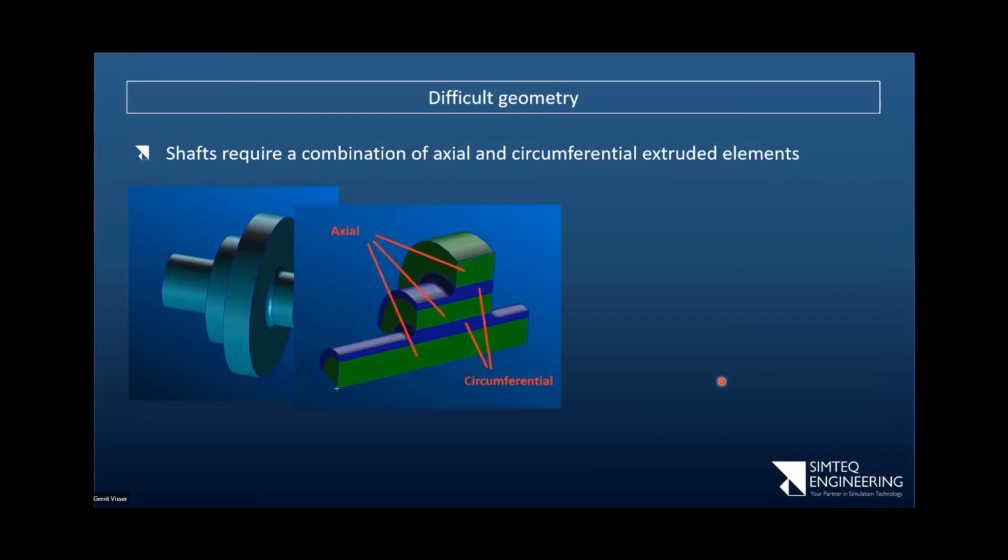The alternative is, if I split this, again, previously I would have meshed this whole section and revolved. Now I start looking at the concept of meshing different parts of it in different directions. The reason I want to do that is if I mesh this and I revolve, no matter at what radius, there's the same number of elements in the circumferential direction. Okay, so if I mesh the green sections and I extrude them, in other words, I mesh this face and